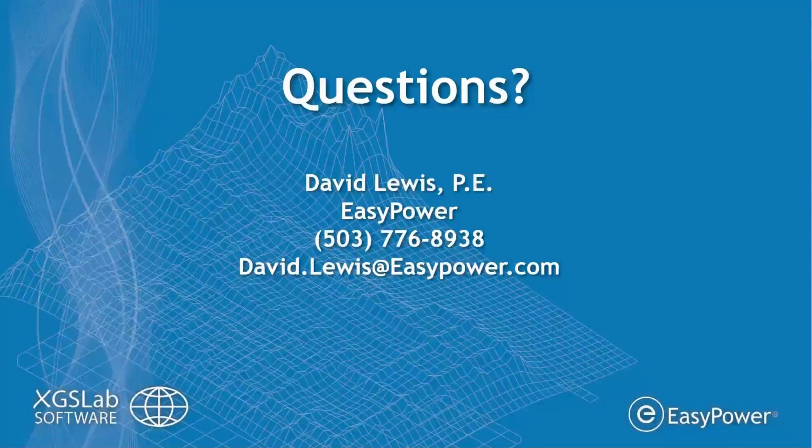They're great for simple applications, and the way you're able to do that sort of calculation is that it assumes your entire grounding system is at the same voltage potential. So if I have a system that is 1 ohm and I have a 1,000 amp fault current, then I have a 1,000 volt potential on that grounding system.